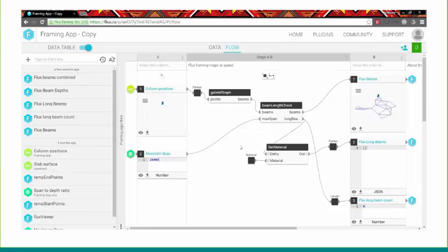One that I remember happening a lot to me was people using different coordinate systems. And so for my structural analysis model, I wanted everything down by the origin. But then the architect had some model which was a few kilometers away from the origin for their own very good reasons. And so, okay, who makes the compromise now? Do I ask them to move the model to where I want it to be, ready for my consumption? And then when I send it back, they undo that transformation? And it just slows everybody down, and actually we all need to work together to design this thing. Why couldn't we automate this step and again have it live in the intermediary position?